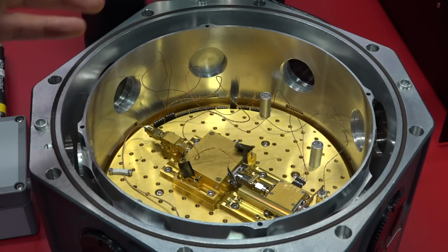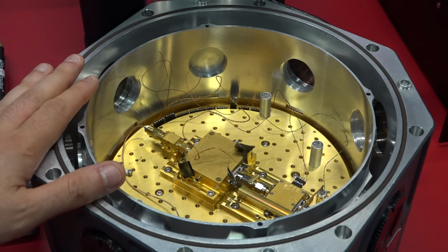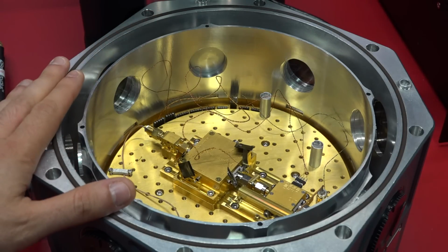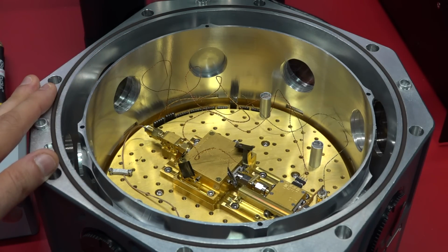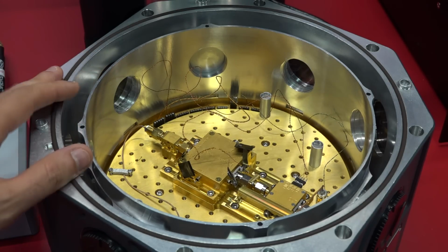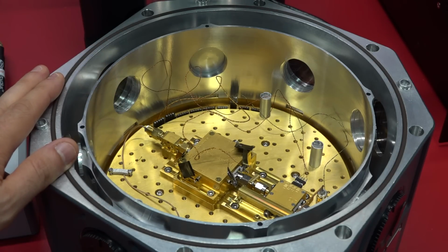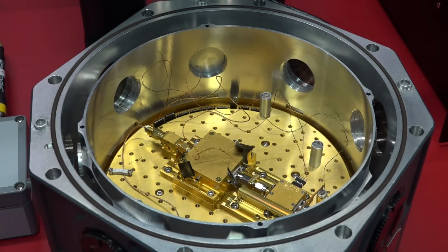So here what we have is completely solid state tuners that are required for noise parameter measurements. It can be enclosed down to 4 Kelvin. So being able to extract these parameters at high frequency, very difficult. So of course these are very esoteric and very specific needs, but if you need to be able to extract noise parameters, particularly for quantum applications, for example, at these frequencies, this is how you do it.